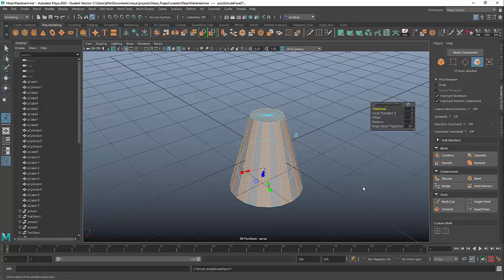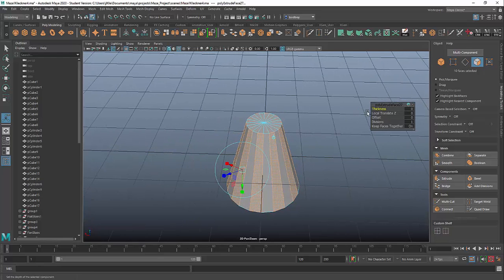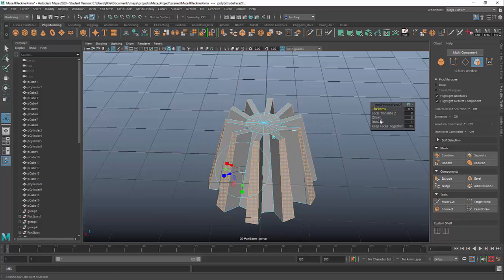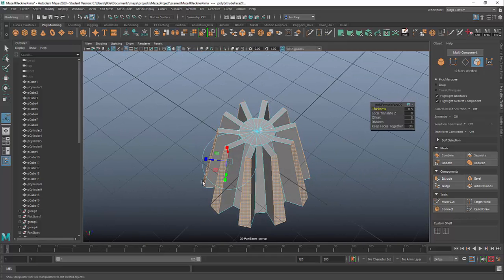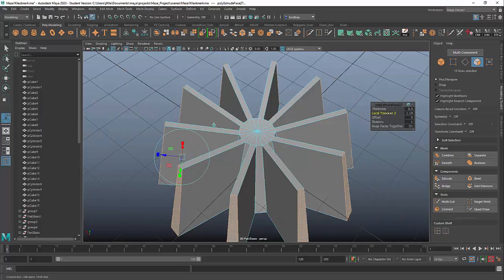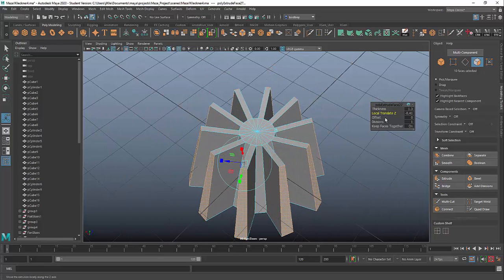What that does is a little pop-up menu appears, and it offers some options. As I move the cursor over there, there's one thing called thickness that I can drag across here. I can also pull out from the blue arrow. Anytime you do the extrude, just remember the blue arrow. That's the one you want to focus on. If I drag this with the blue arrow, I'm translating it in the local Z axis. So the thickness is pulling it out, and then I'm translating it by pushing out in that local Z.